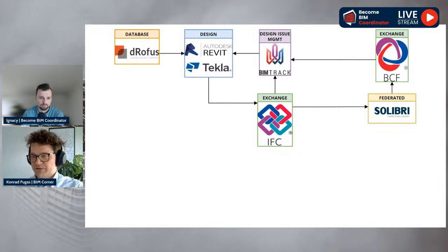Every Friday, there is an automatic IFC export for all models, and during the weekend every platform is fed with fresh models. Solibri is one of these platforms. We federate all models in this software. In the design process, we use it for quality assurance and clash control, both internally within the design team and for communication with the building owner or contractors.